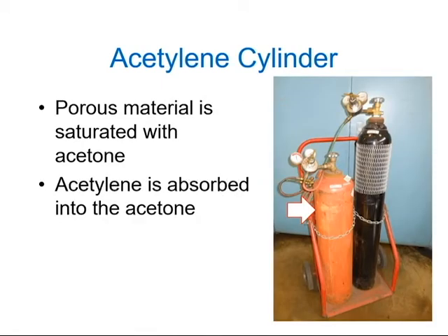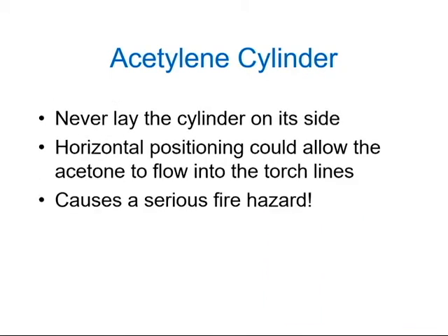As mentioned before, acetylene is dissolved into the acetone, and that mixture gets held by the porous material, which is housed within the cylinder. Always keep the cylinder upright, because if it's laying down, that could potentially cause the acetone to leak out and create a very serious fire hazard.